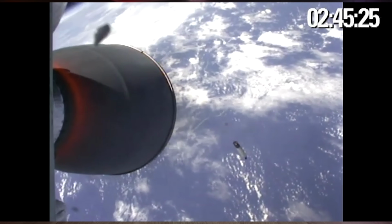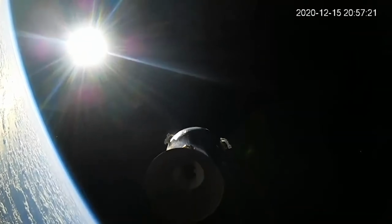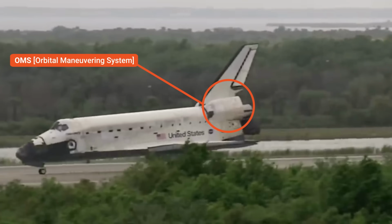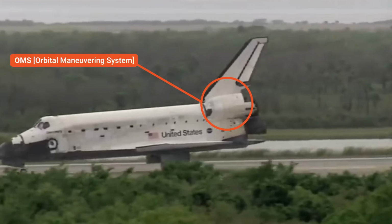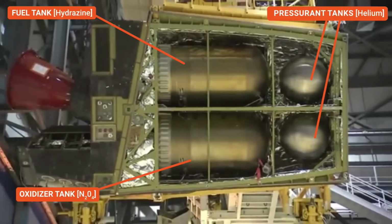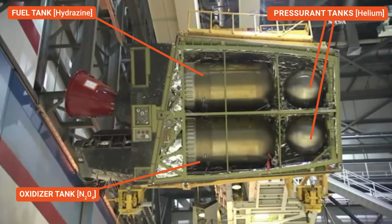But that being said, many rockets have utilized pressure-fed upper stages, such as SpaceX's Falcon 1 upper stage with the Kestrel engine, or Astra's Ether engine on their second stage. But the Space Shuttle's OMS pod, or the Orbital Maneuvering System, is maybe the best and most simplified look at a bipropellant pressure-fed system. We can clearly see the two pressurant tanks, a fuel tank, and an oxidizer tank, all right there, laid out perfectly.